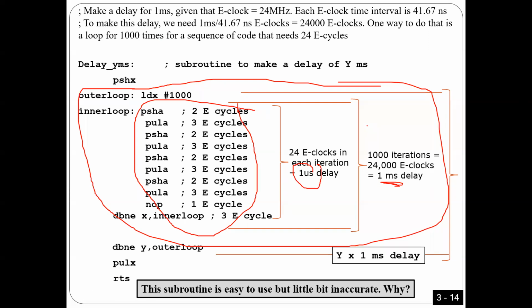And now, how much delay do you want? I want a Y millisecond delay. This part here makes 1 millisecond, so I'm going to repeat it Y times. That's what I did. Look here, guys. I have a block of instructions that takes 1 millisecond, and I repeat it Y times. You can see this is how it works. Any questions?